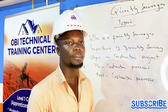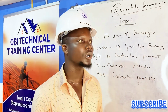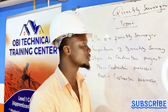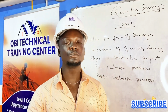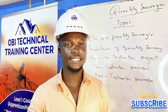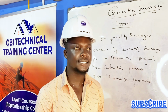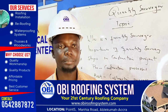And with the plants and equipment, the quantity surveyor is able to determine that we need this plant to do this work, and this plant will take this number of days, weeks, or months on the site. Based on that, the quantity surveyor is able to do an approximate estimate to know how long the machine or equipment will be on the site and how expensive it is going to be. We do this analysis to determine whether the machine is going to be hired or purchased.